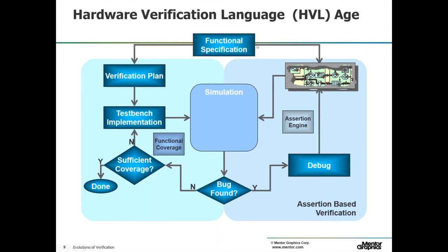I have this requirement, and it's maybe these 2 assertions and this cover directive or cover point. These are things that you write, so it's not automatic like code coverage, but these are things that I write to say, I am looking for this activity, I'm looking for this temporal relationship between these signals. If I see that, that indicates that some portion of a requirement is correct.